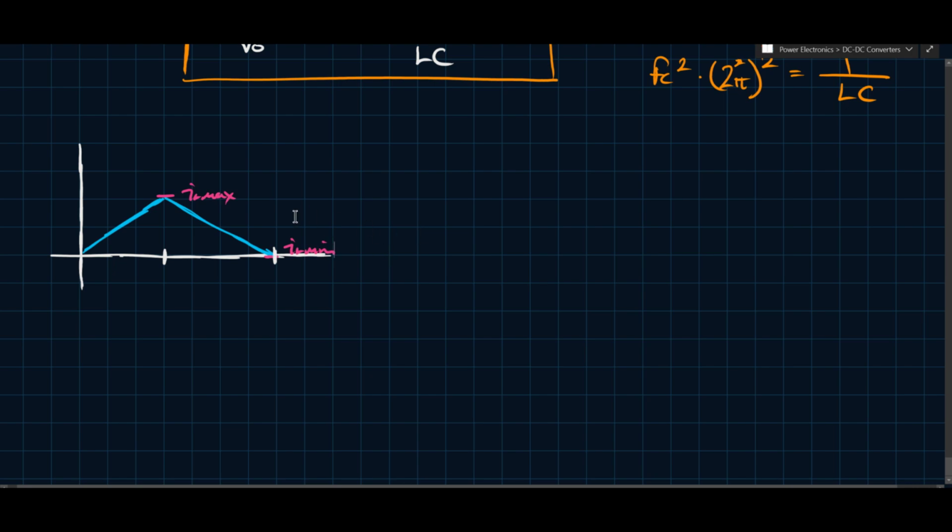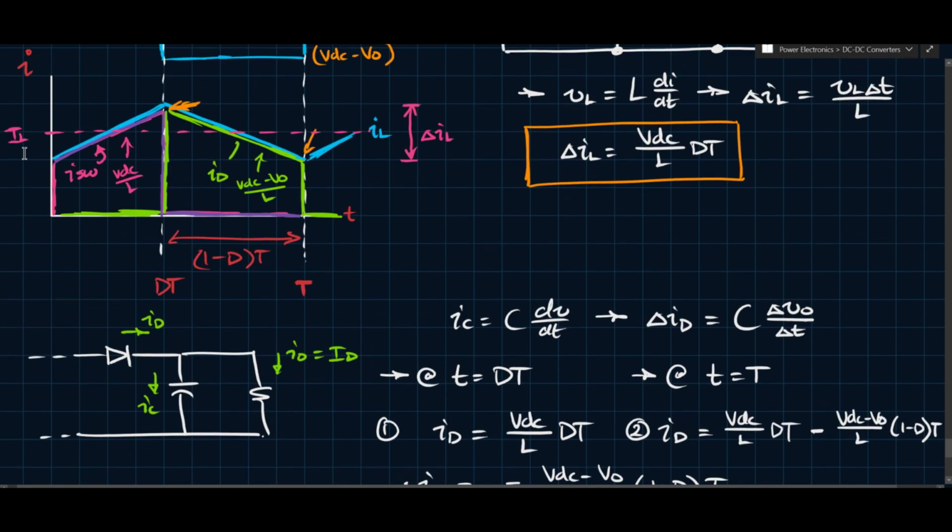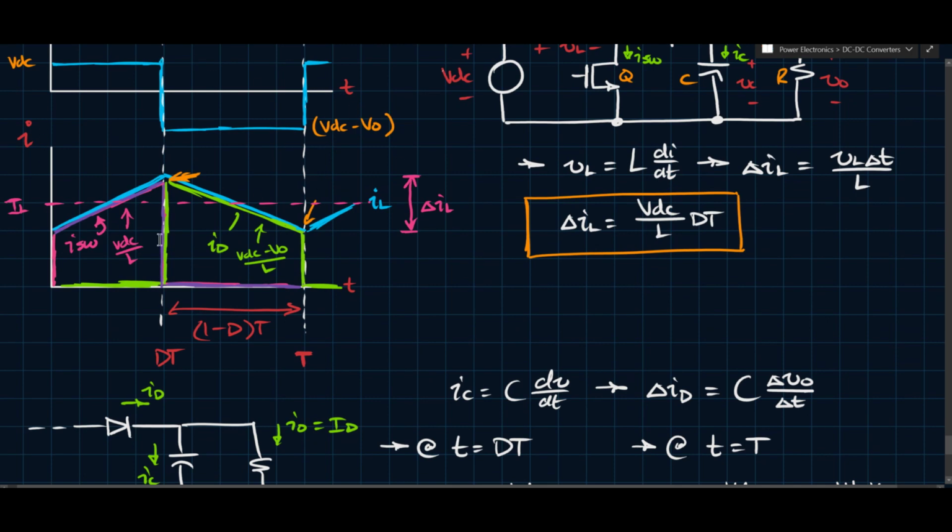is 0. And so if we go back up to our other waveforms, this is continuous mode, right? So this is the continuous conduction mode. And the continuous conduction mode, again, just simply implies that the current conducts through the inductor continuously. So this current, this blue line, never reaches 0. But what happens sometimes is this average will decrease. It'll start to drop because your output conditions change.